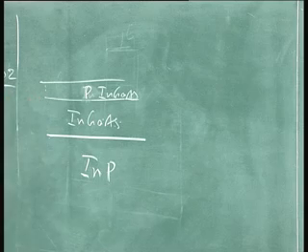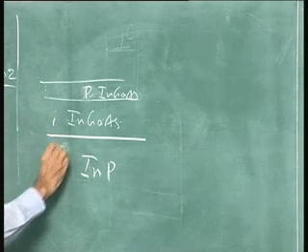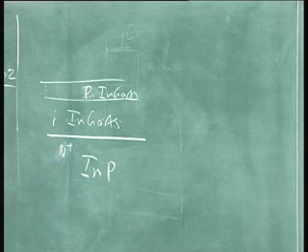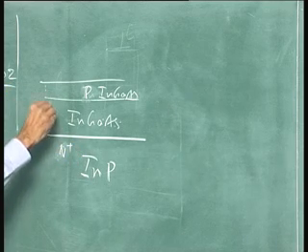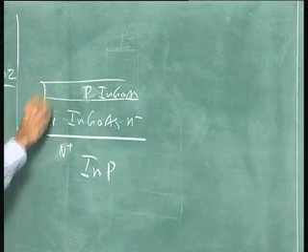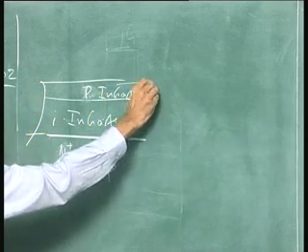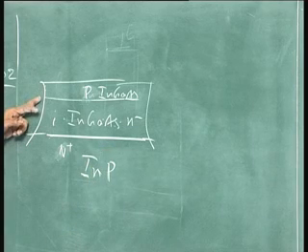So, p type, this is intrinsic, this is p type, I am sorry, n plus. These are different layers which are there. So, what I want to try and point out is this is slightly n minus. So, then you prepare it and etch them down like this. So, you have the junction exposed here.